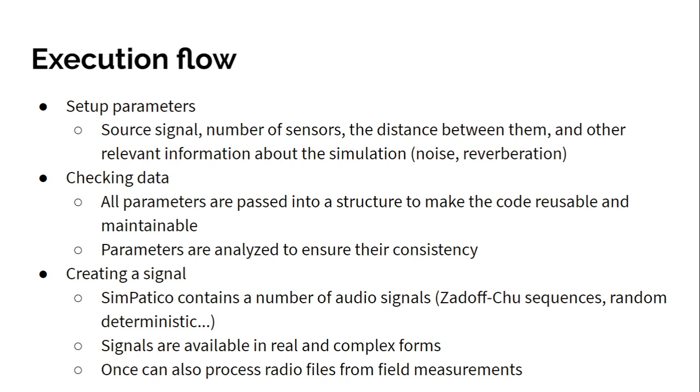For example, here we can set up the algorithms we want to use, the type of signal. That can be a gong, signal, chirps, just a sine wave. It can also be an audio file given by the user, for instance. We can configure the distance between the source signal and the sensors, the distance between the sensors, source frequency, sampling frequency, number of iterations, propagation speed, noise channel, and so on. There are many things that you can work with.